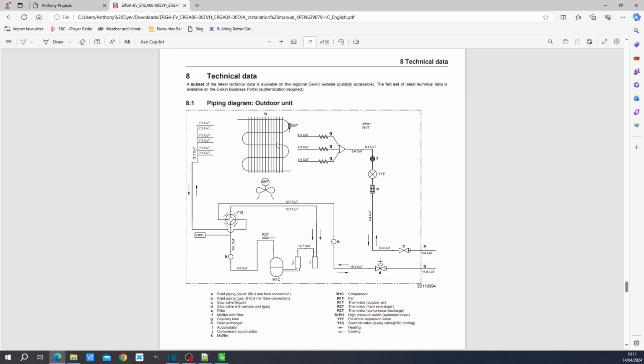So in this heat exchanger, it sees an expansion in the volume, and as a result, the liquid then turns into a gas. And in the process of turning into a gas, it is absorbing latent heat from the environment, and this is where the flow of air is needed. And then it returns back here as a low temperature gas.